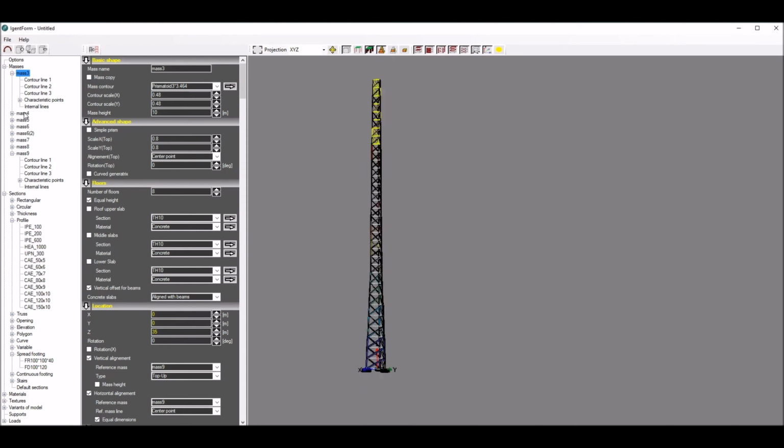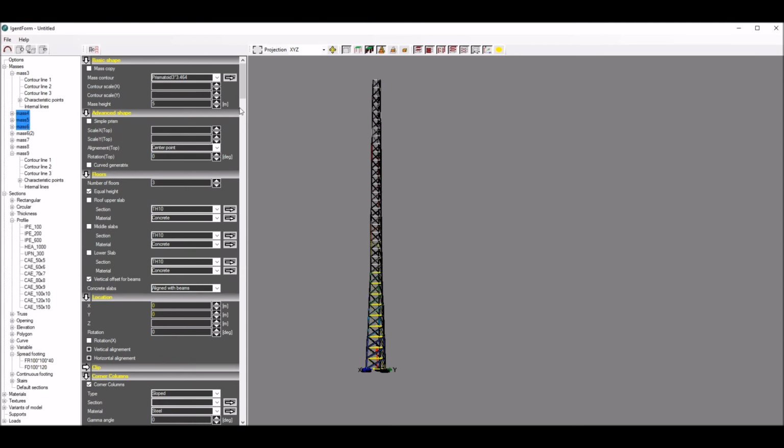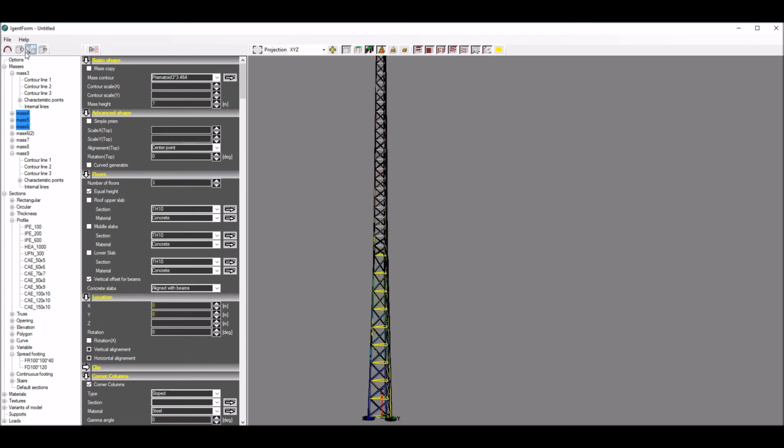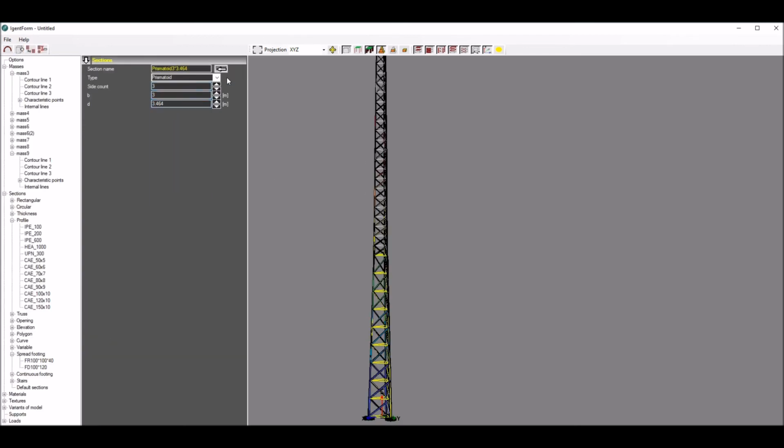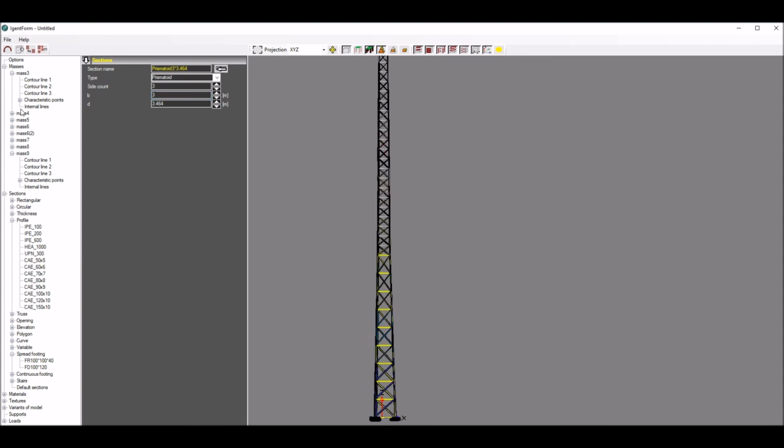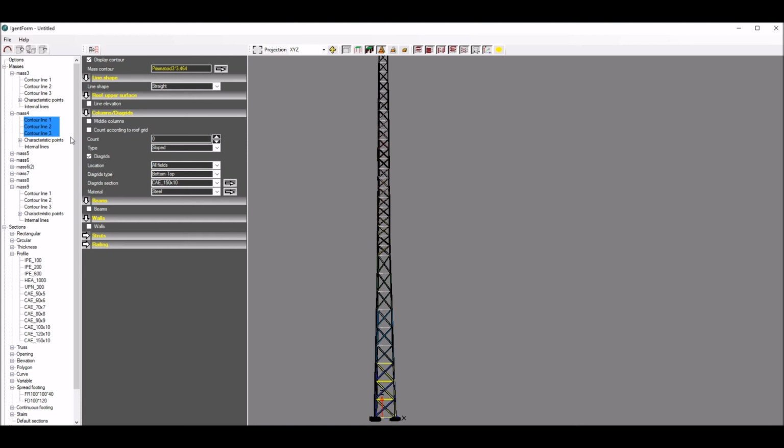Before defining the wind load case and sending the model to Autodesk Robot Structural Analysis, I would like now to emphasize the power of the parametric model. Namely, if we would like to change the geometry of the tower, we can do it quite easily. For example, we can change the height of segments. To do it, it is sufficient to make a multi-selection of chosen segments and set another height. Thanks to appropriate vertical alignment relations, the whole model is automatically rebuilt.